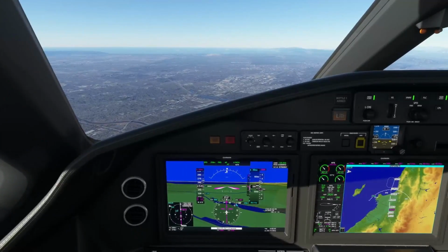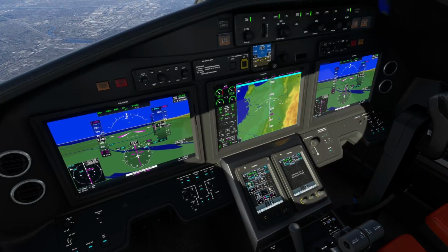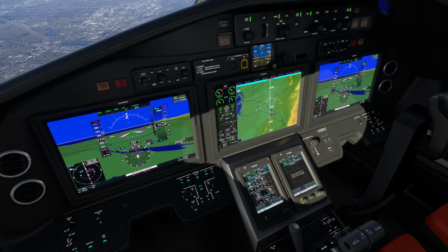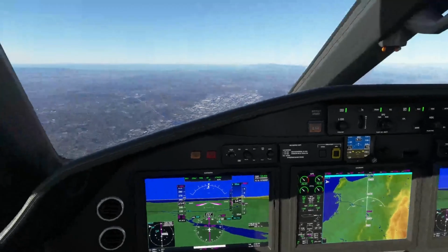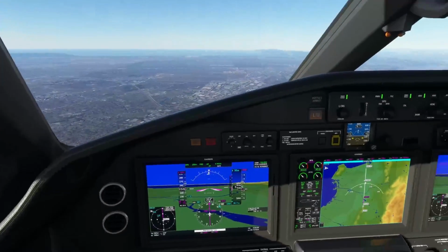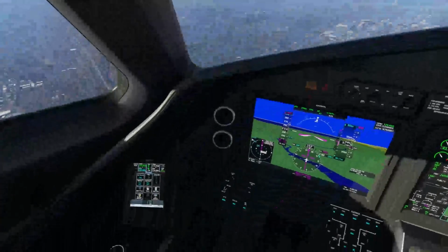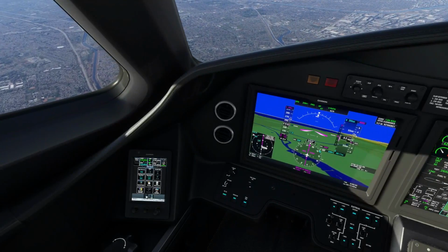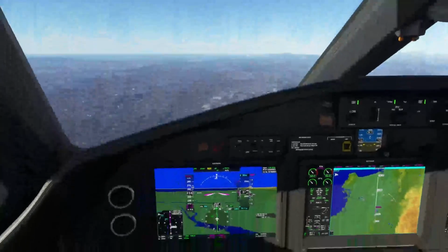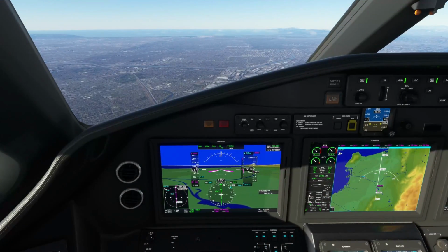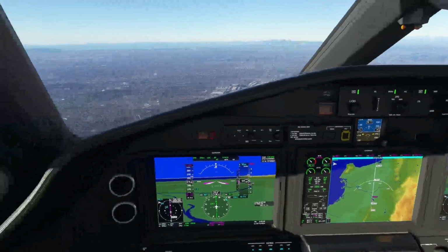And let's see here. What's our distance to the airport now? Now about 20 miles. So I'll tell you what, let's do approach mode. Oh, no, I can't do approach mode yet. Disregard. Let's do nav source. There's the localizer. Right on track. Approach mode.